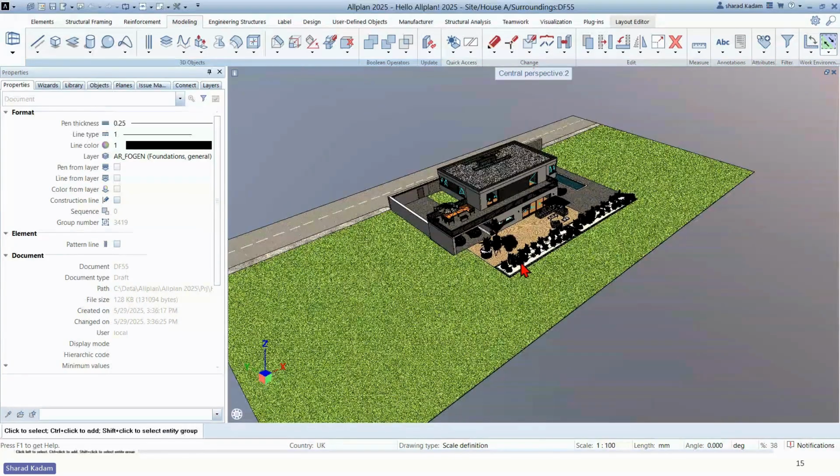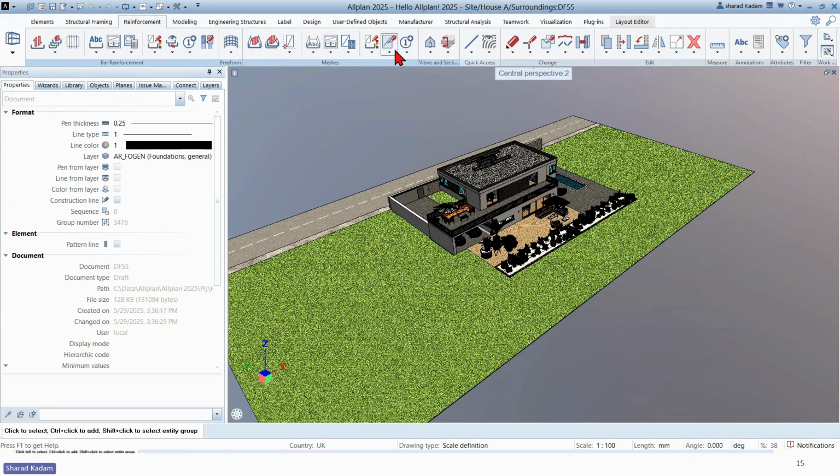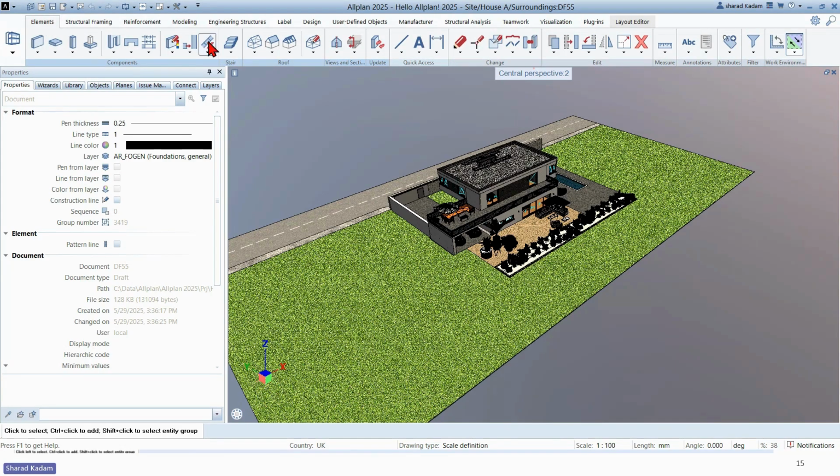So when we start with the outline, we have various features like architectural, engineering, and surrounding drafts. The architectural portion is mainly for the architectural part, which we won't be talking much about. Engineering is the segment wherein we do the complete rebar detailing. So I'm just clicking on this engineering portion. Once we click on it, we get the tools which are needed for rebar modeling and the tools which are needed for the element modeling.